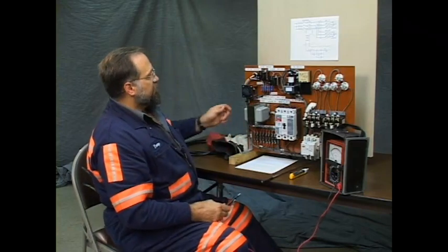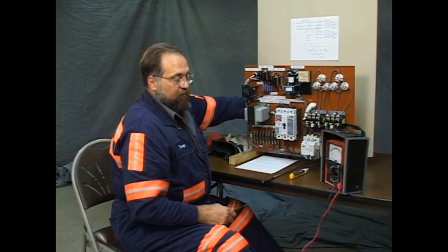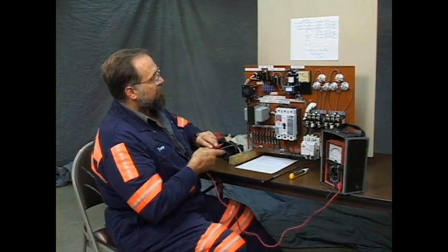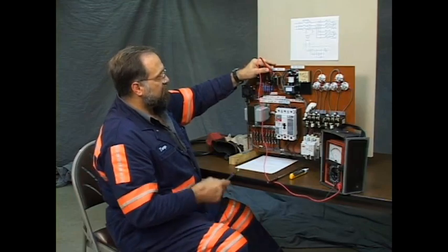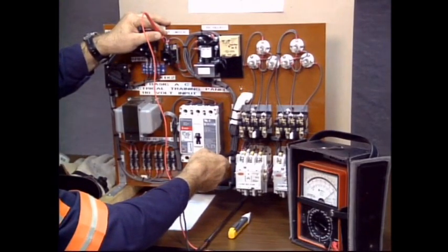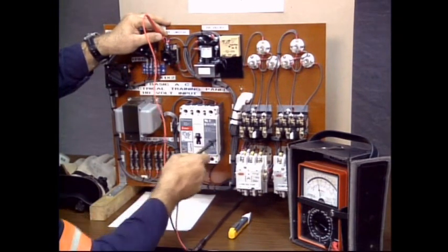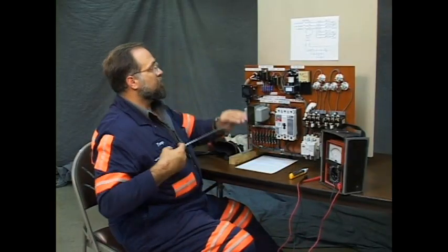Let's toggle the switch here just to make sure. You remember that before it read open. The wire read open. Let's check it now. Line side of the start switch, A auxiliary. Now with the problem toggled, with the problem removed, it shows continuity, it shows a circuit. With that wire open, the holding circuit is defeated.